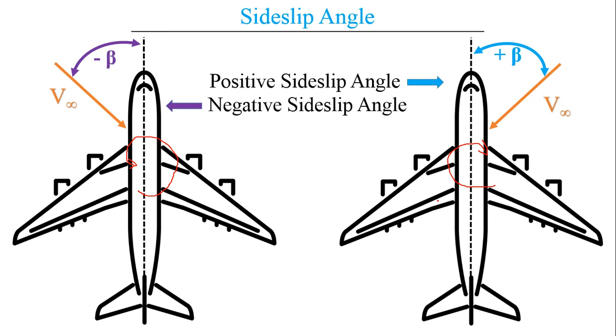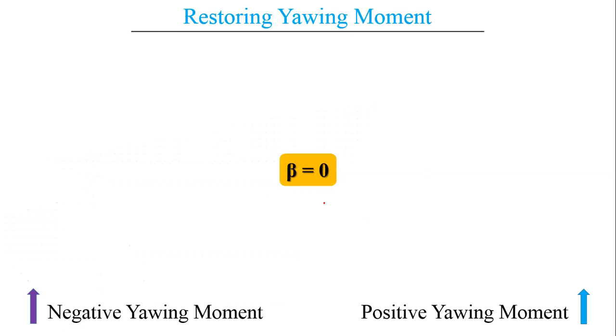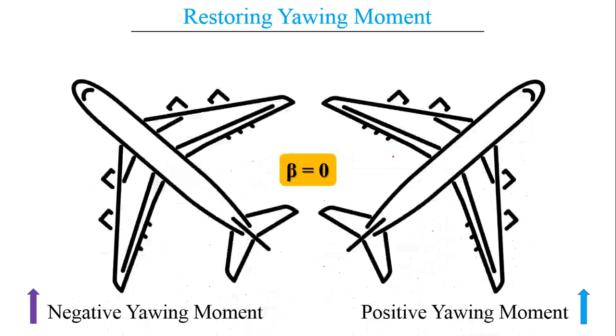So when the aircraft is tilted, the aircraft will be oriented towards the side slip angle or relative wind, and the aircraft will still be moving in this direction. This is evident in crosswind landings. Now let's see how an aircraft flies during a side slip angle. This is a short animation. Here we can see the aircraft was tilted towards the relative wind. Still, the aircraft was moving in this direction.